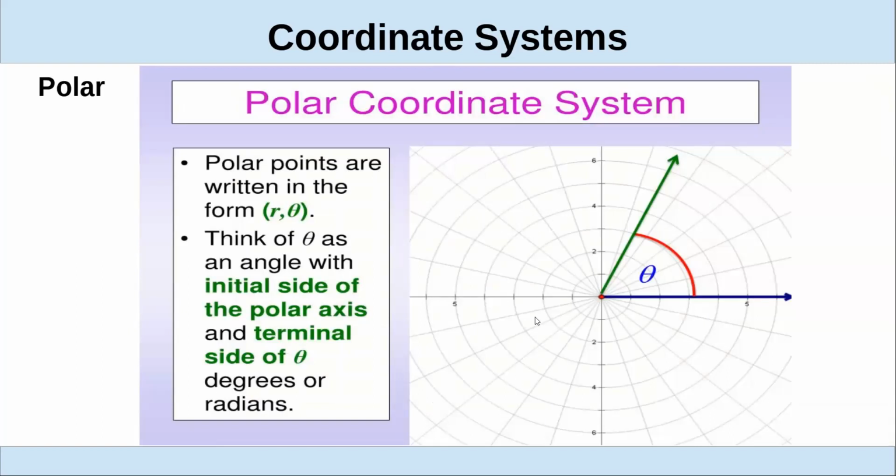Sometimes we use a polar coordinate system, usually in antennas, to show radiation patterns, possibly with impedance vectors where you're going to represent it as a length and an angle. Normally you see it as the real plus the imaginary as a rectangular coordinate. Sometimes it'll represent it as a value at an angle of a certain amount.